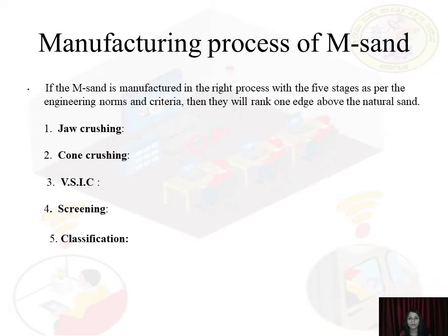How is this M sand going to be manufactured? What is the basic material? Stones. Crushed stones are used for the manufacturing process of this M sand. The production usually involves a series of stone crushers and screeners to filter the crushed aggregates to an accepted size.